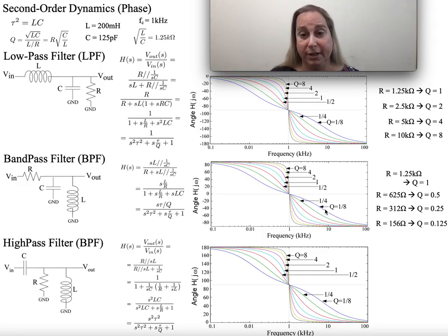I expect it's going to be dropping down. And by the way, I can look at when the angle would have been 45 degrees and ask, what's the value at 45, how far off in frequency? Well, that's going to basically be about a factor of 8 from that center. And that's exactly what I would expect. If I look at it for 4, it's going to be about a factor of 4 from the center, so it's about 0.25. And in fact, yes, that's what I see there, about exactly where I would expect it as well.